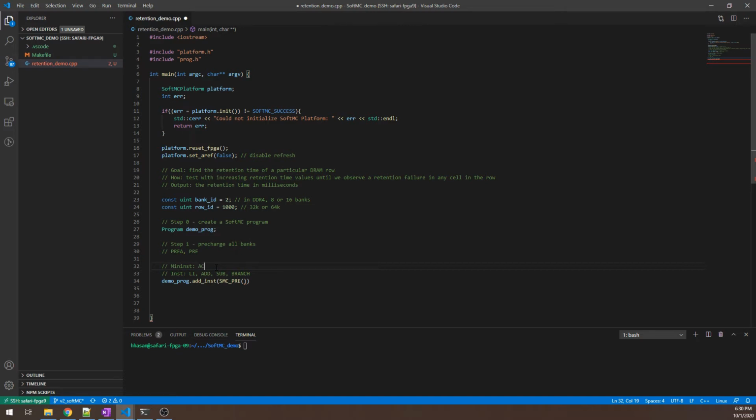So just as an example, like activate, precharge, read, and write. And the reason we have two different sets of instructions over here is because FPGA logic is not designed to achieve, or cannot work at, very high frequencies, but we want to be able to use the DRAM with very high throughput, so we can achieve much better bandwidth when we access it.